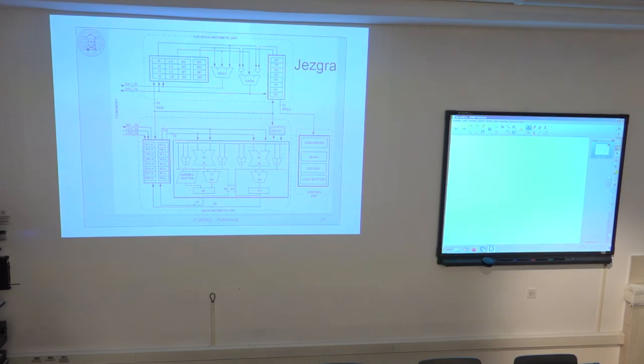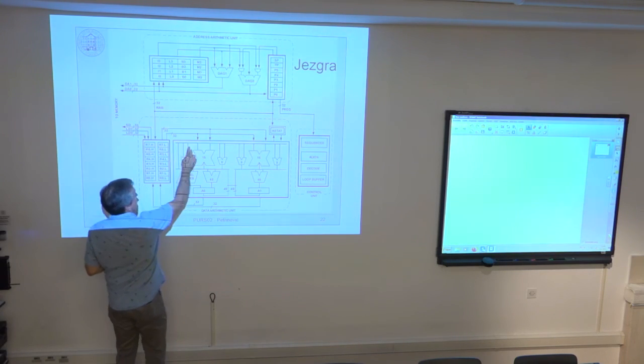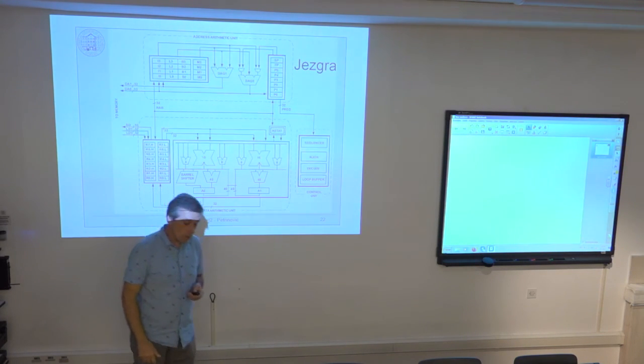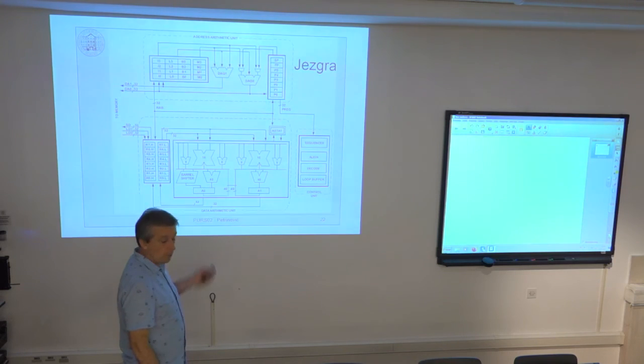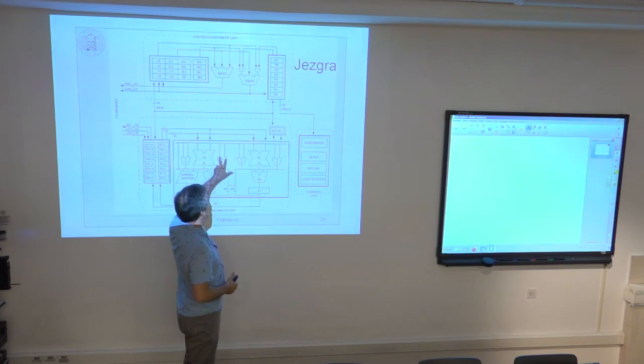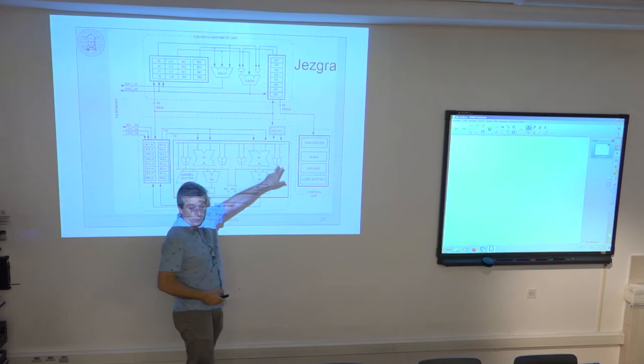And these 64 bits can be treated as one vector of 4 times 8 bits and another vector of 4 times 8 bits. So in this case, I would like to add the first 8 bits of the first vector to the second vector, okay? And I get the 8-bit result for the first entry of these two vectors. Then the same thing for the second entry of the input vectors, the third entry, the fourth entry.